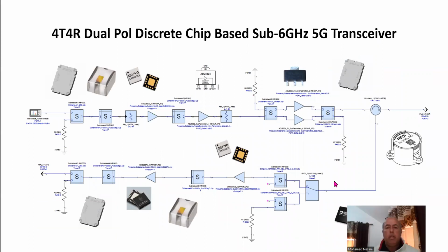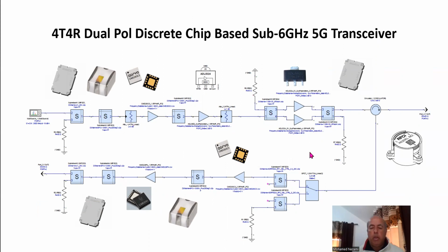What we did is basically, here's the transceiver design. All the components were picked off the shelf. And by the way, the last time when I simulated this, we were assuming that we are operating in an ideal situation where we had a margin for basically the loss between the stages, the interconnecting stages to all of these devices, and the copper. Somebody emailed me and wrote that you need more than this. Yes, true. This is only a top level calculator, and this would have to be done schematic based, and then PCB layout, and then simulated with ADS, and that's the next set of videos that we're going to do.